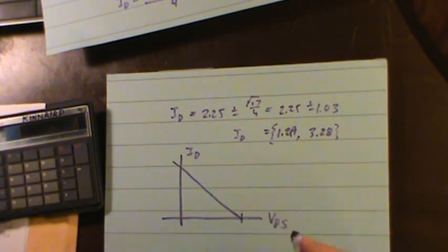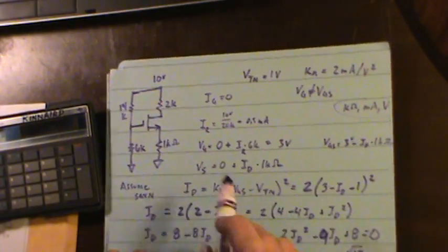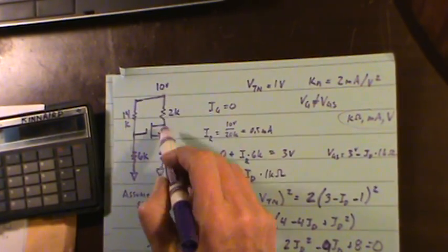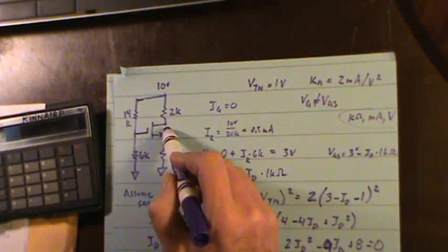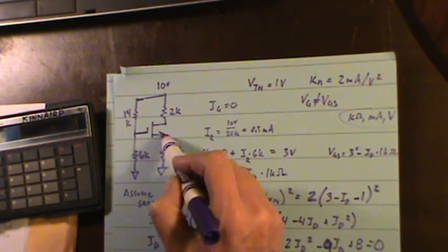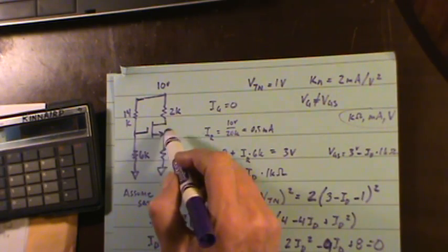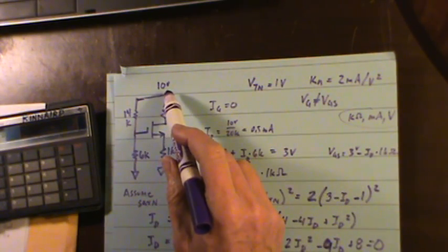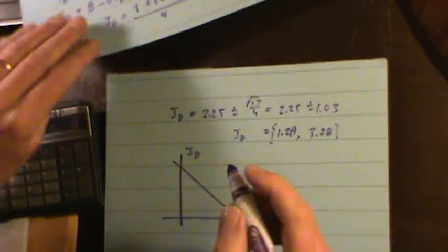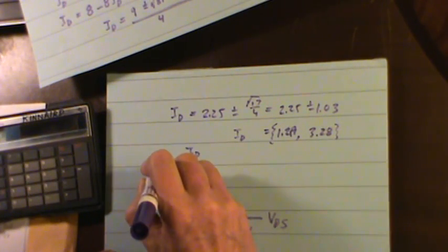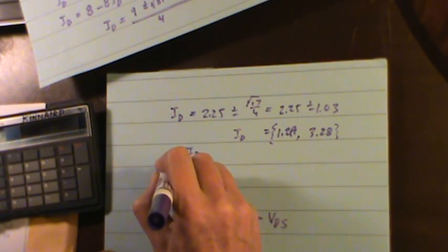Okay, so anyway, the most voltage that could be across there is 10 volts. The most current: I've got 10 volts up there, I've got 0 down there, and if this were a dead short, if this were short circuited, I'd have 3k ohms in between. 10 divided by 3 is 3.33 milliamps.